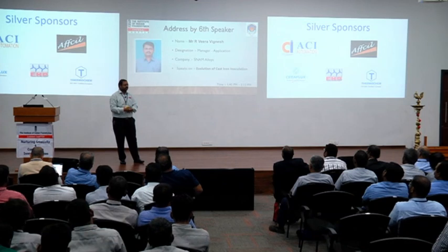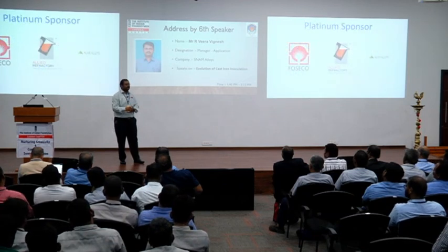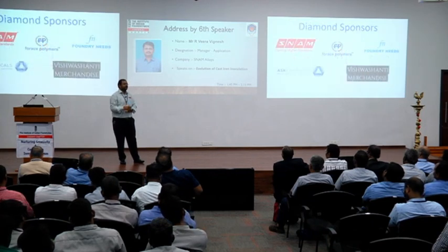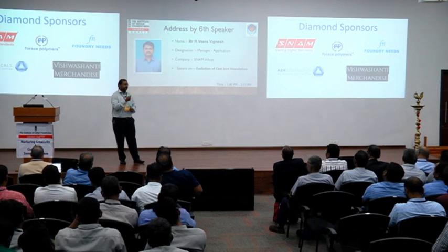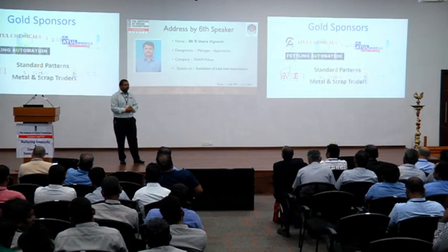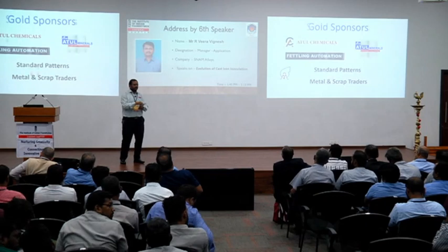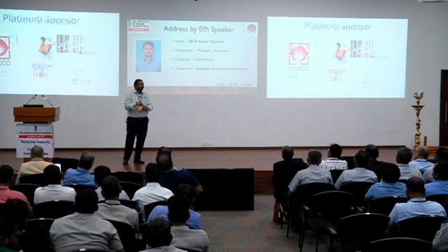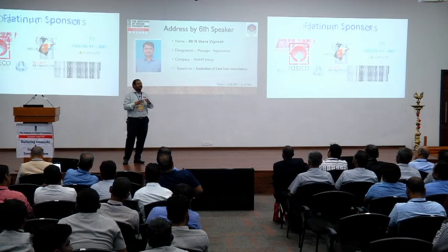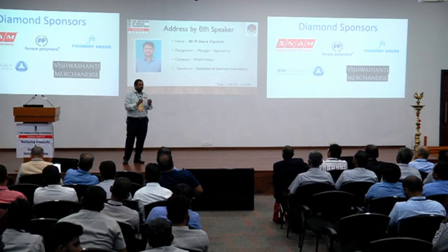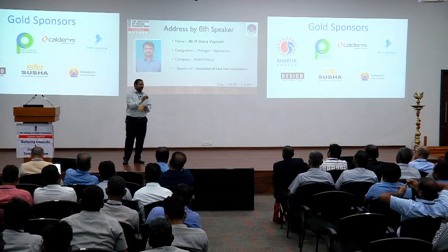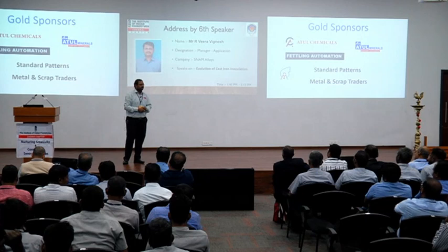So what we can ensure in our liquid metal or even our solidification is, we can avoid forming network of carbides of all these elements. It is not just molybdenum carbide that gives you failure. It is the network of molybdenum carbides which is giving you failure. So if we understand why networking of molybdenum carbides happens, it is the cooling rate of casting that decides how the molybdenum carbide forms. Generally, all these carbide forming elements will be located around the grain boundaries. So if we can ensure that our cooling rate of the casting is maintained such that the molybdenum carbides are not pushed towards the grain boundaries or sudden chilling does not happen, we can avoid the severity of molybdenum, chromium, vanadium, these carbide forming elements.